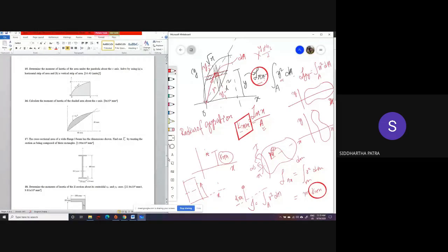Okay, now that origin obviously depends on where you take your coordinate system. If this is your coordinate system, then that is the origin. O prime is your origin instead of O. So therefore this quantity is x squared plus y squared times dA. Okay, so basically it is Iyy plus Ixx in that given coordinate system. Sum of these two quantities in that given coordinate system.